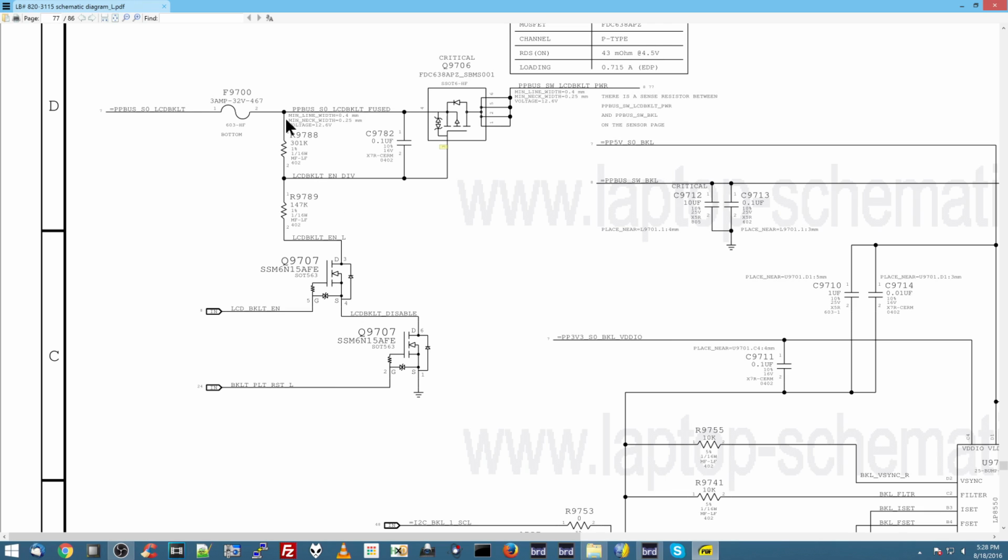So some voltage is going to go here, but then by putting a resistor to ground, and this resistor over here is a much lower resistance than the top one, a lot of the current is going to flow to ground, but not all of it, which is then going to lower the voltage. So again, if I simply put a resistor to ground over here, if I just take this resistor from here and put it to ground, it's not going to lower the voltage because this has a lot of capability to deliver current.